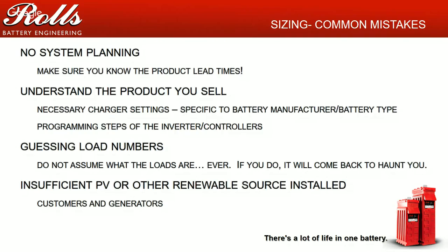Don't ever, regardless of the battery, use the manufacturer's default settings for the inverters and the charge controllers, because if you do, I can guarantee you that those settings are going to fail. Be careful with that, and make sure your customers and everybody knows the system.